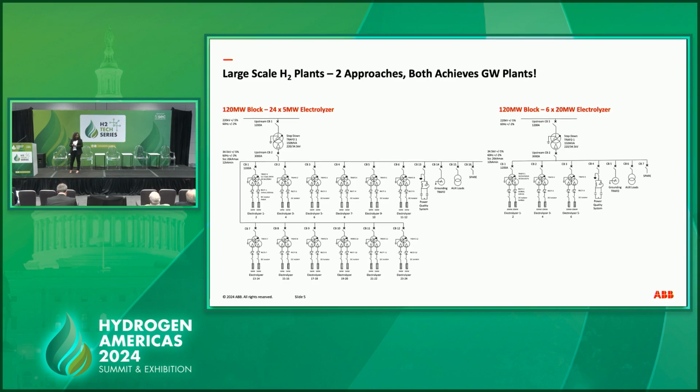To explain the setup, each electrolyzer is connected to one rectifier, and then two of the rectifiers, which are 6 pulse each, are packaged together and connected to one 12 pulse transformer. From the transformer upwards, we have the MV switchgear, and then, to maintain a common basis for the sake of comparison, the HV switchgear is the same.